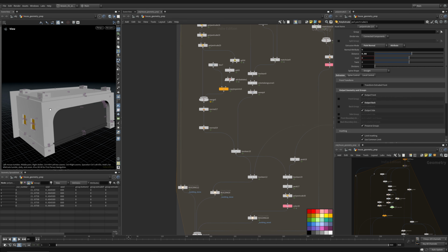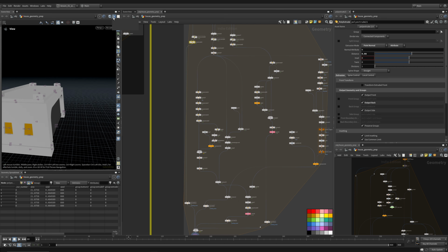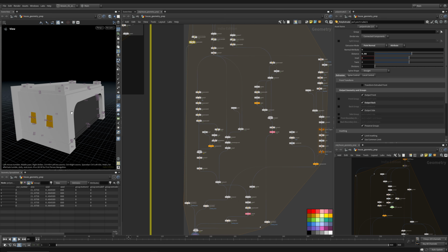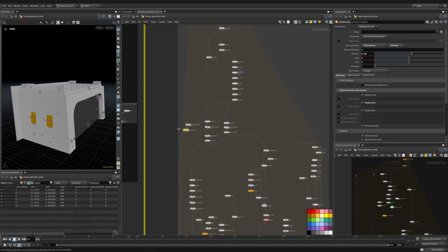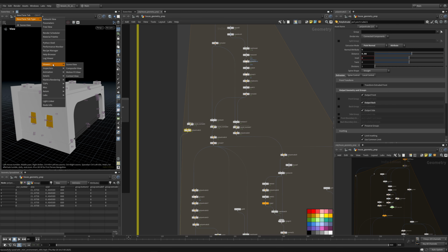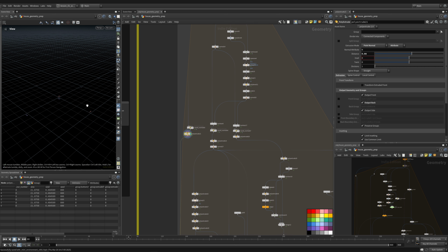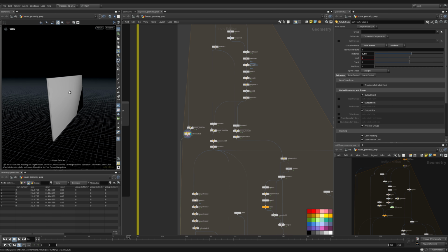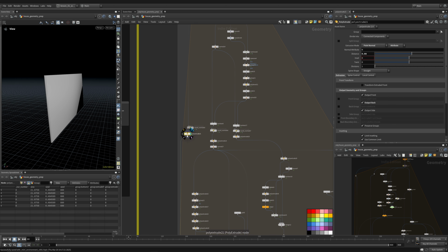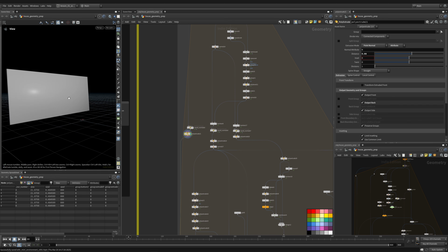Looks like my scene, again, is running a little bit slower. So we'll see if I can fix this. We'll try resetting the scene view. So I'm going to do a new pane type, viewer scene view. I'm going to X out this one, repin this to 1, and ghost or hide other objects. Select our node, and I'm going to hit space G. This sort of sped it up a little bit, but if I do need to restart, I will again. So we'll see how that goes.